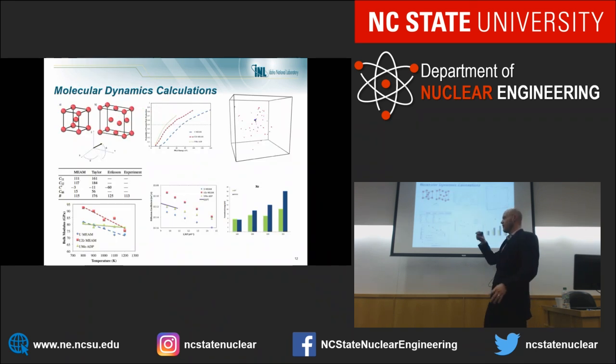So uranium's hard and odd. So we've taken all that work and we made interatomic potentials for the pure uranium system first. We've looked at a variety of things. One of the more recent fundamental studies that we've done is looking at the threshold displacement energy in gamma U and alpha U and how that changes. We looked at it at a variety of directions as well, analyzing how low symmetry directions versus high symmetry directions affect the displacement energy, and also how the interatomic potential of choice affects the displacement energy as well.